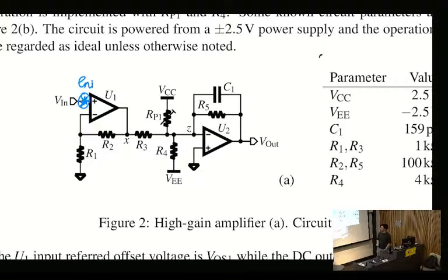Yes. So one thing we can do is use a diode, which will clamp the voltage at a particular value, which means whatever the reference voltage is now, let's say it's a 0.7 volt diode, the reference voltage is now 0.7 volts rather than VCC. So VCC powers that diode, no doubt, but the specific value of the reference voltage has nothing to do with VCC anymore. It's now clamped to 0.7 volts. So it's loosely dependent on VCC now.